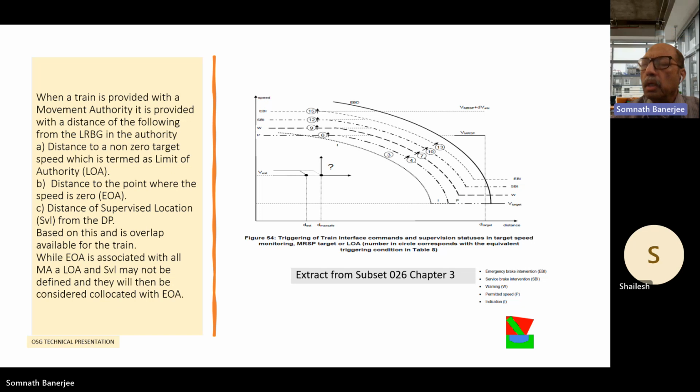Thereafter, the train monitors what is known as the release speed. The release speed ensures that a train will not go beyond the end of authority under any condition. Where the end of authority does not have an overlap, the release speed is lower than what can be provided when there is an overlap, because of the manner in which a train can be controlled to be brought to an absolutely safe stop at the end of authority.